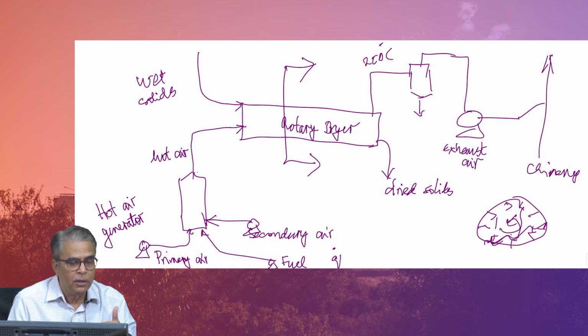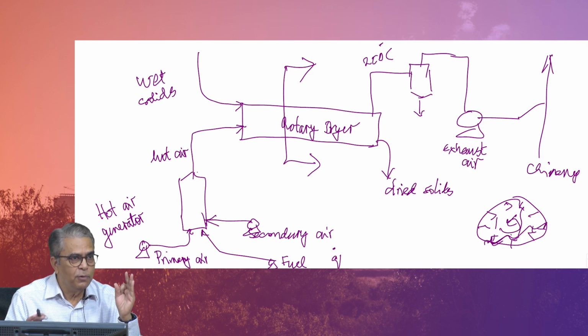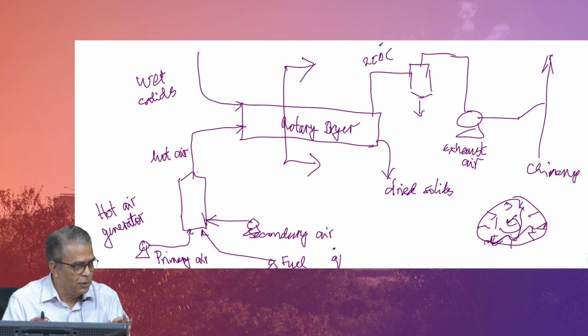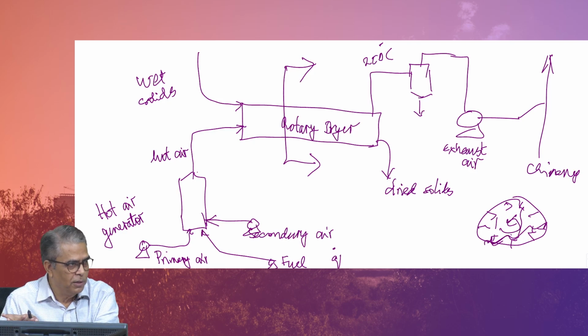Second, you will assume the burner is such that it completely burns the fuel to CO2, because if the fuel gets burnt to CO, you will require a different quantity of air, but then it is incomplete, you have not recovered the entire heat value from the fuel. So, using these two pieces of information you can find the theoretical quantity of air, which only means that under proper conditions, this is the absolute minimum quantity of air required to burn the diesel into CO2 and H2O.